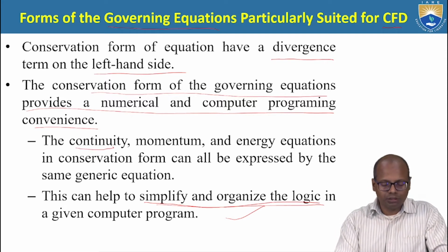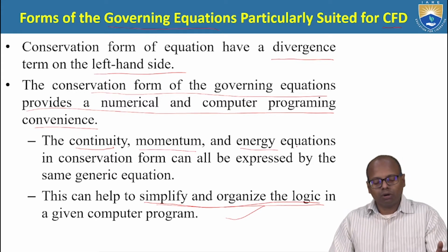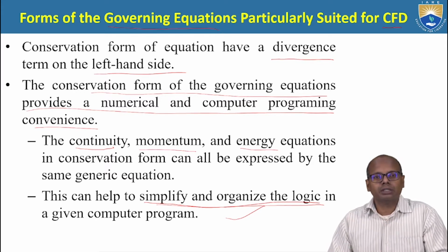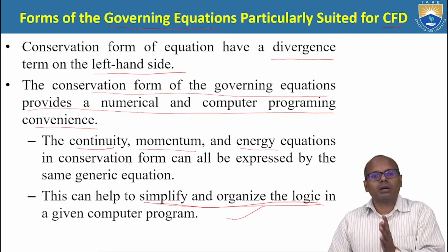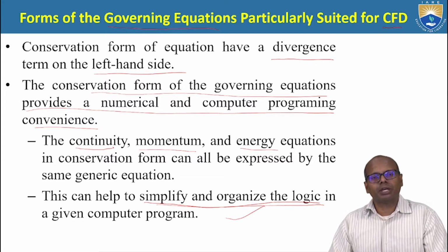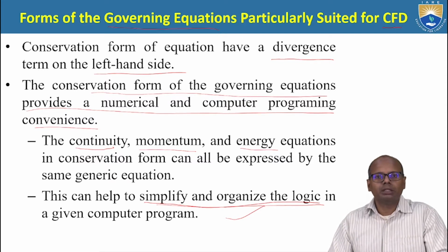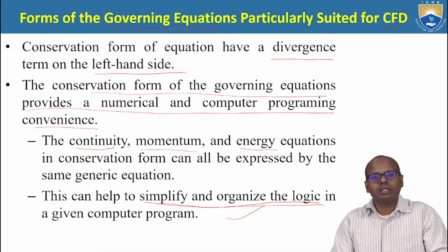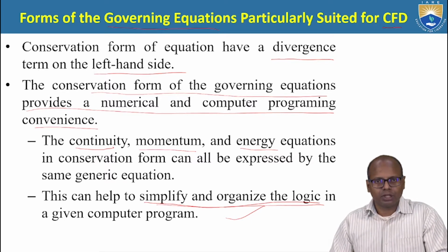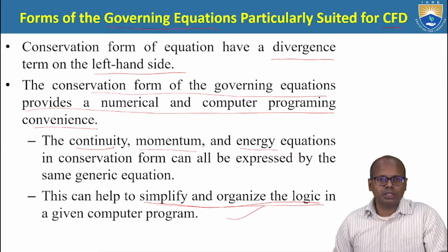We have the continuity equation, we have three momentum equations, we have the energy equation. So all these five equations, if they can be expressed in the same form, then the logic or the code that we develop can be easily organized. That is the reason we are doing this exercise.